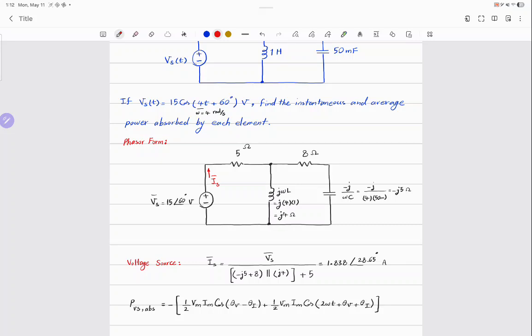Here is the reason for that. You're interested in the physical answer, not the mathematical, right? Let me give you the mathematical one. So you have some voltage, and the average is 0. But if you square it, then the average is not 0 anymore. So that's the mathematical answer. What's the physical answer? What's the meaning of a sinusoidal voltage or current? It means that sometimes it's going from left to right through the resistor, sometimes half a period it's going from right to left. But does it matter for the resistor? No, because in both scenarios, it's going to absorb. So do you see where the non-zero average comes from?